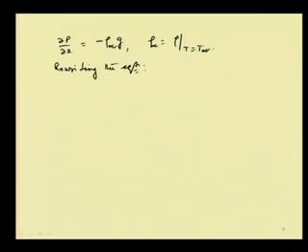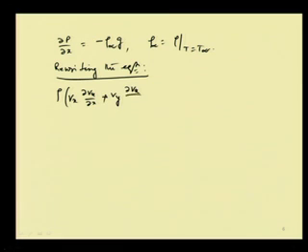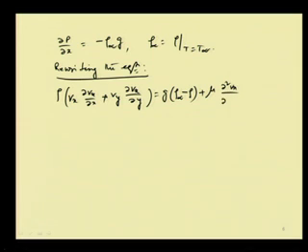So, therefore, rewriting the equation, we get rho into Vx into del Vx by del x plus Vy into del Vx by del y equals g into (rho infinity minus rho) plus mu into del square Vx by del y square.